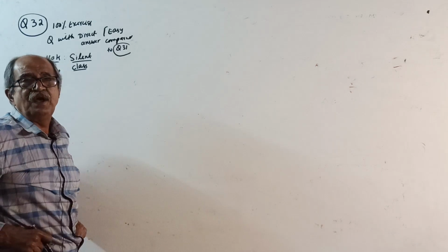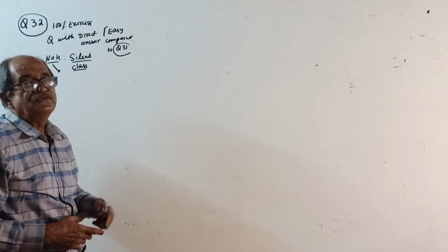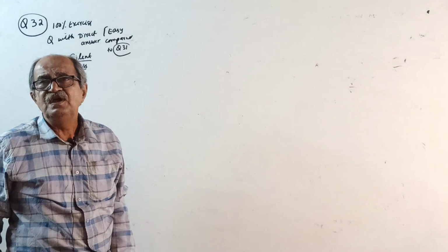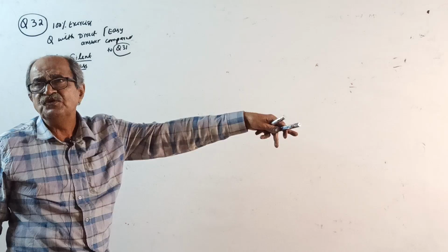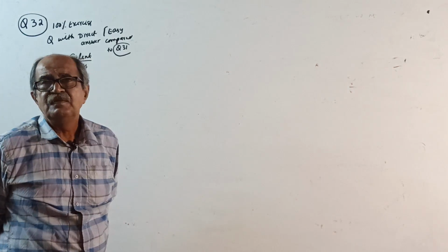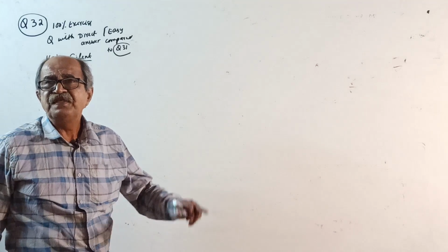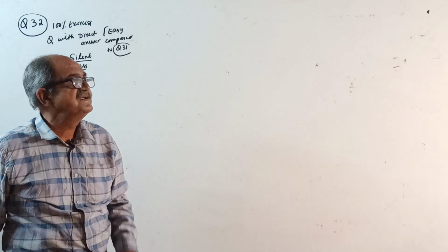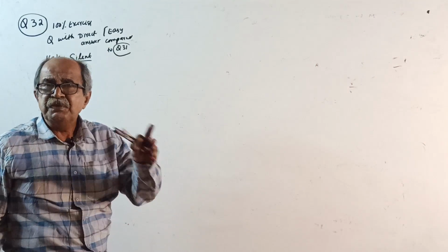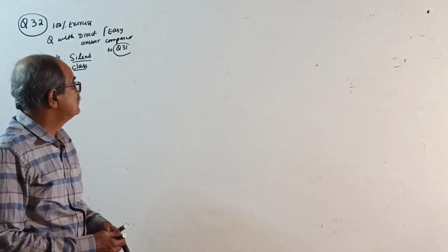But 1 minute before I go silent, solve it the same as that question. First find axial forces, then using the axial forces come and find reactions, then separately find reactions. Okay, that's all.